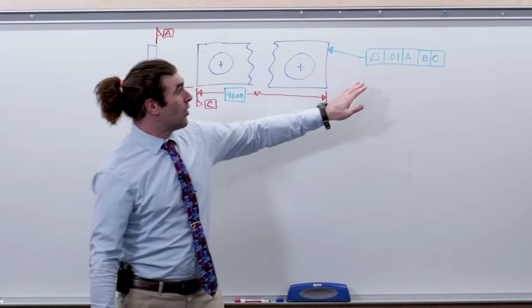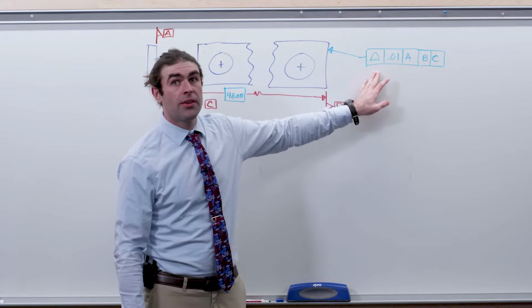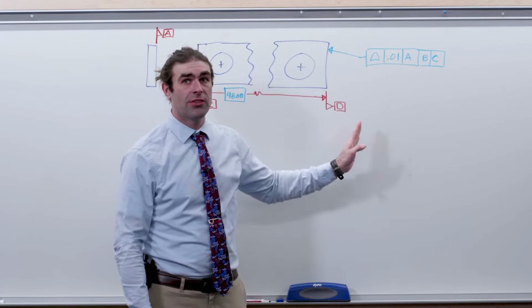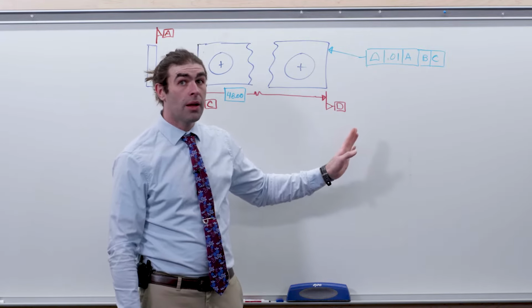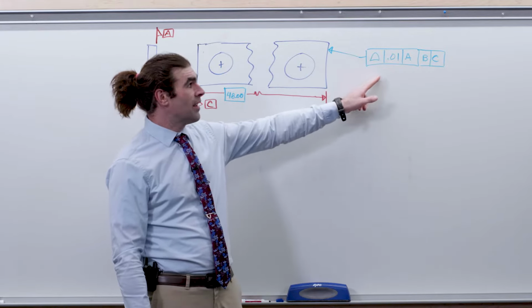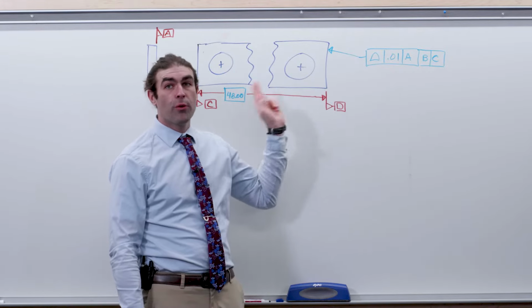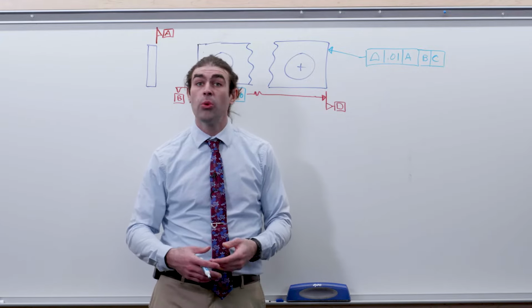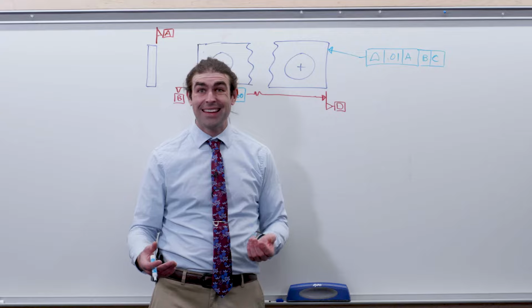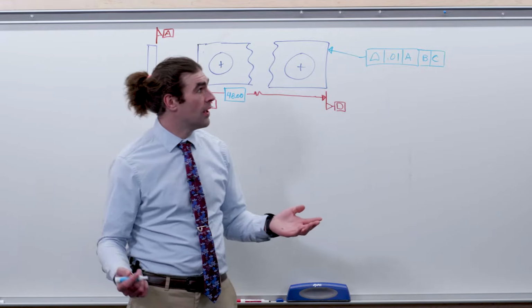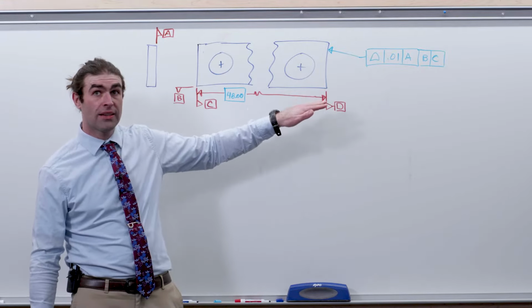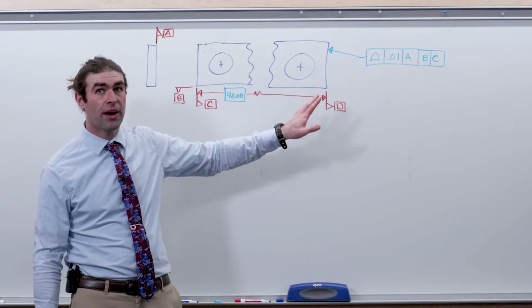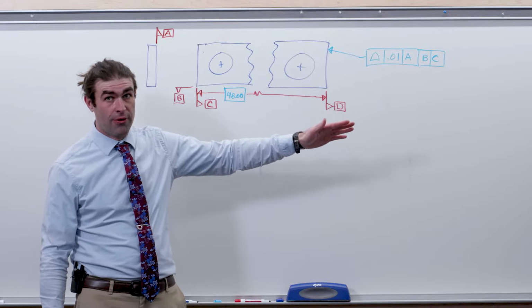Okay, our first option, profile to A, B, C, will establish D just fine. But measuring a profile of 10 thousandths from 48 inches away could be difficult, right? We might want to open up that tolerance to make it easier to inspect. This is the most restrictive we can be, a single profile to our datum reference frame.